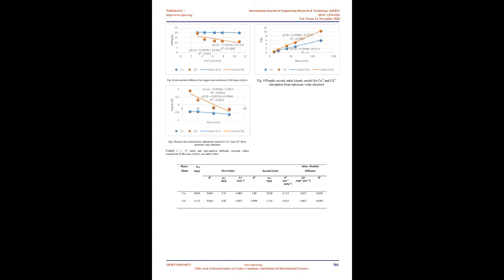The amount of adsorbate ranged from 3.98 mg/g to 20.45 mg/g within 10 minutes for initial concentrations of 1 to 5 mg/L of copper salt solution, where the final concentration obtained was Cf equals 0, and after 120 minutes the quantity of adsorbate ranged from 3.98 mg/g to 20.09 mg/g respectively. In contrast, for cadmium salt solution the adsorbed amount ranged from 4.36 mg/g to 19.65 mg/g at 10 minutes with final concentration Cf equals 0, and at equilibrium the quantity of adsorbent showed 3.4 mg/g to 11.42 mg/g.